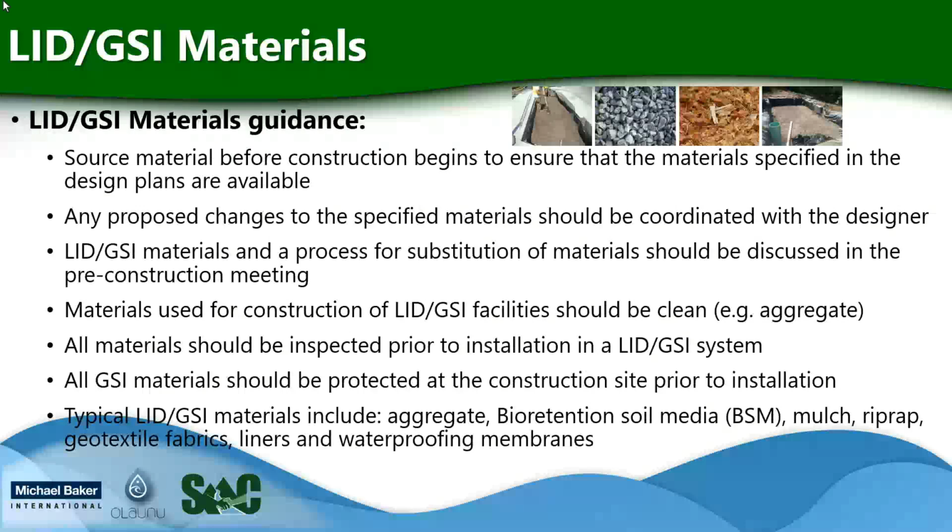Guidance associated with these materials includes source material before construction begins to ensure that the materials specified in the design plans are actually available. Please note that there may be longer lead times for these types of materials. Any proposed changes to the specified materials should be coordinated with the designer. And the materials and a process for substitution of materials should be discussed in the pre-construction meeting.